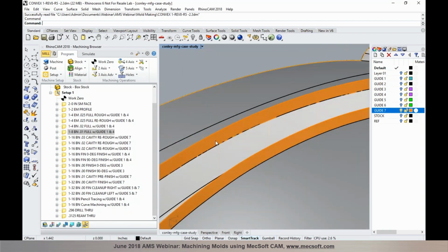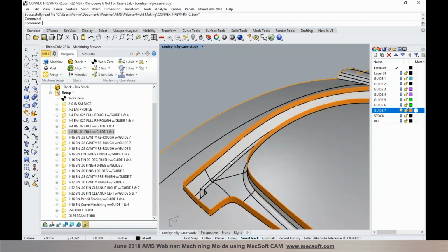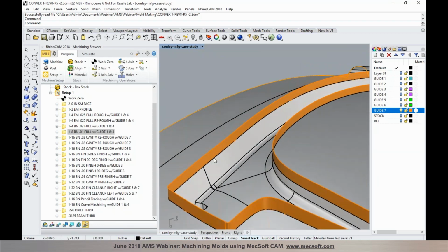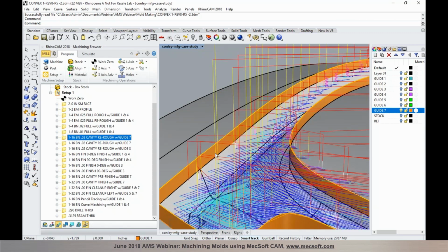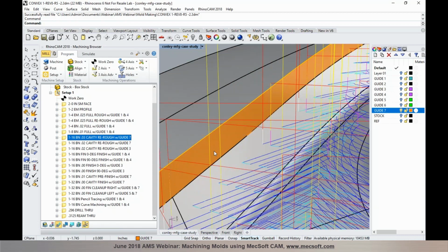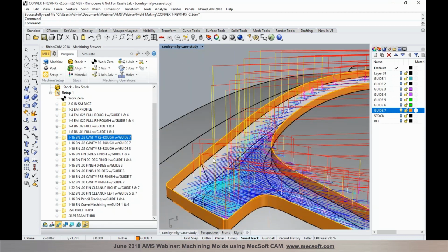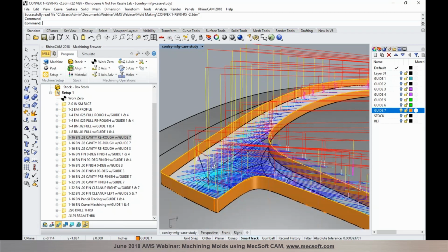So the wall surface has been extended up in the z-axis, as you can see, and these extensions can be equal to a tool radius or the tool diameter of the largest cutter you plan to use for programming these cavity regions in here. So these surfaces can be extended by at least your cutter radius or cutter diameter, so that the tool path you generate will go past it, and this will result in a nice sharp edge and not having to roll over to the adjacent surfaces.